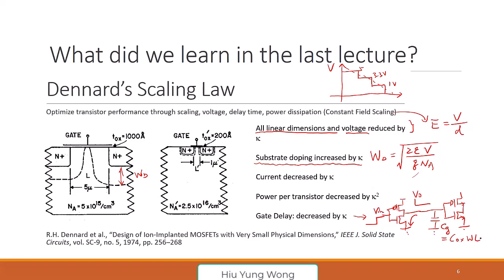So you remember when you're scaling, I make my transistor smaller and weaker. See that? Current is reduced by a factor. But at the same time, I make the loading smaller also. And that's why my gate delay decreased by the same factor, right? But I keep emphasizing that nowadays, it is not dominated by C ox. It also has parasitic capacitance, right? This is not just gate capacitance.